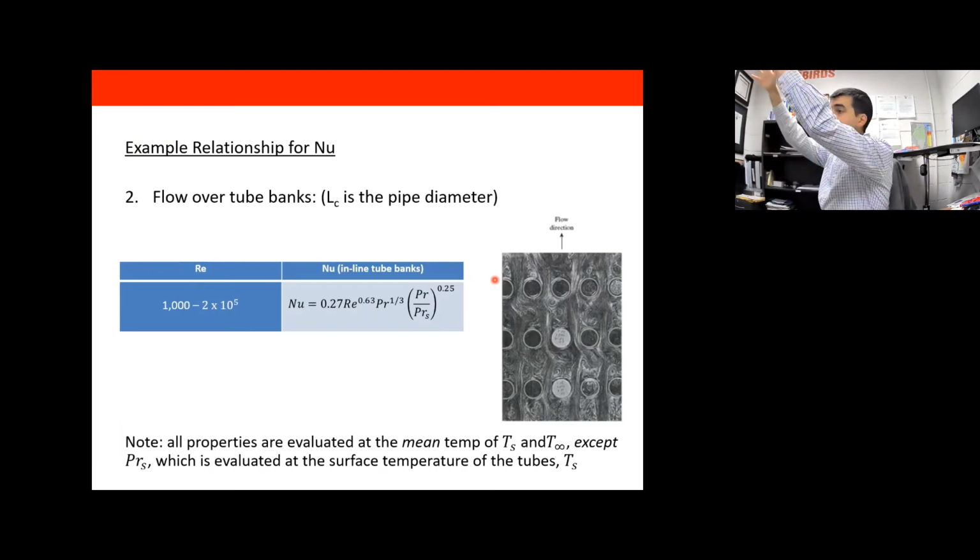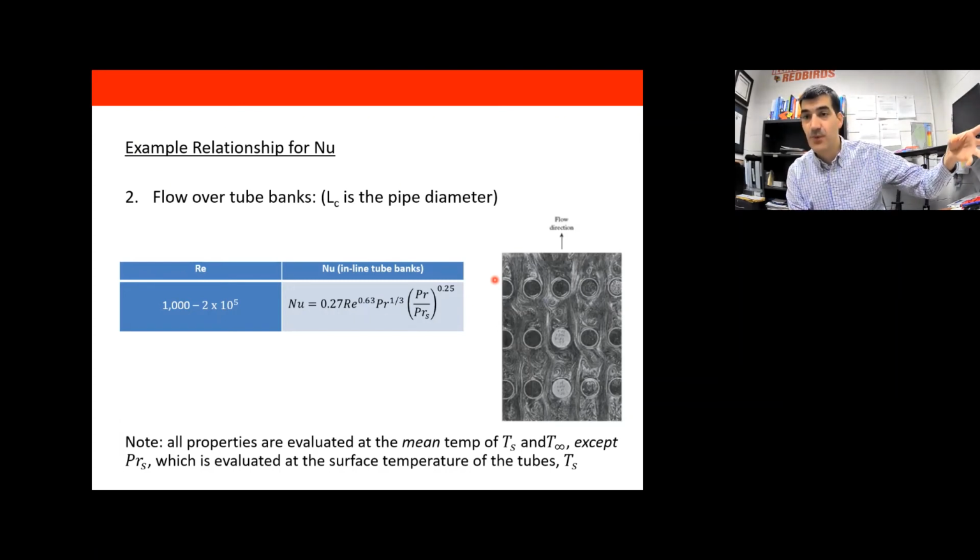And then our steam comes down around the tubes and condenses on the surface of the tubes. So we've got hundreds to thousands of tubes called a tube bank inside the condenser. And usually the same thing inside the boiler as well, just with something hot going through the tubes to boil the liquid that's outside the tubes.